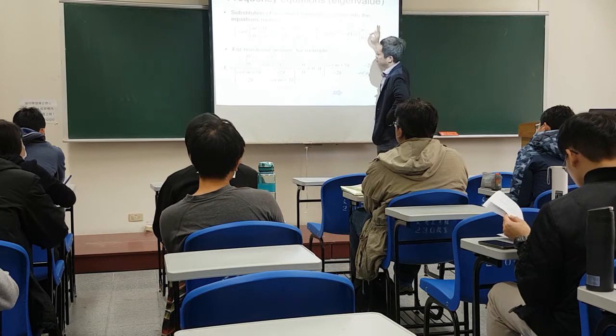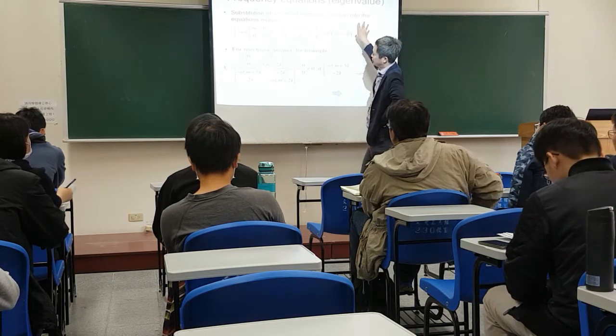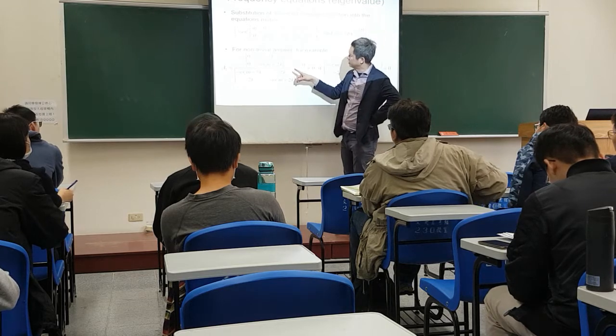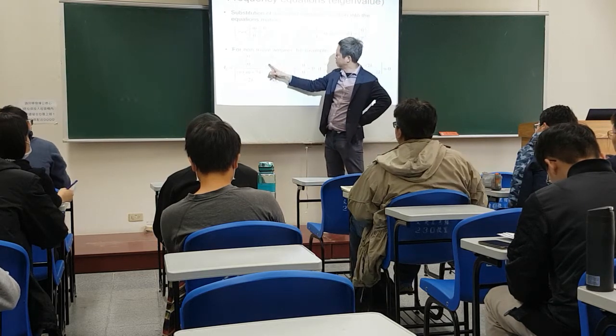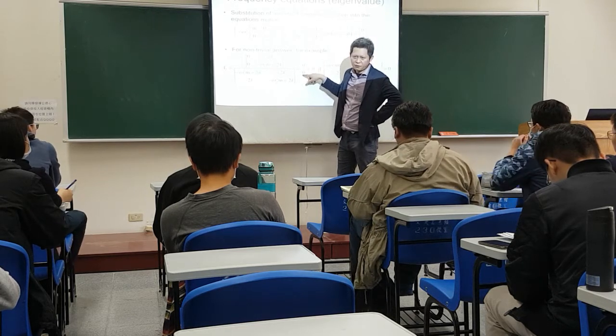You're going to have zero amplitude of vibration, but you are not allowing zero amplitude of vibration, otherwise the solution will be trivial. So in order to do so, even though the numerator is zero, you force the denominator to zero.